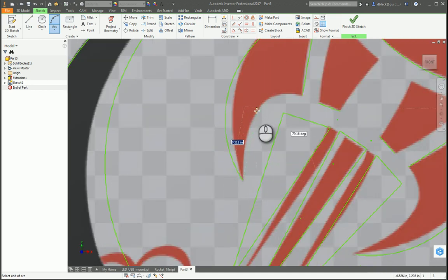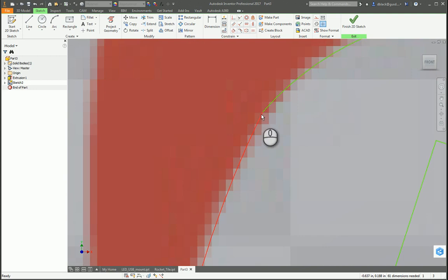I think this one ends here. Try to avoid snapping to other things that might cause you trouble in the geometry. So I'm going to just push that back and try to carry this on from here to this line, and that's a pretty close approximation, but I can see these two don't come together real great. So I'm going to try a tangent constraint on those, and let's see what we get.